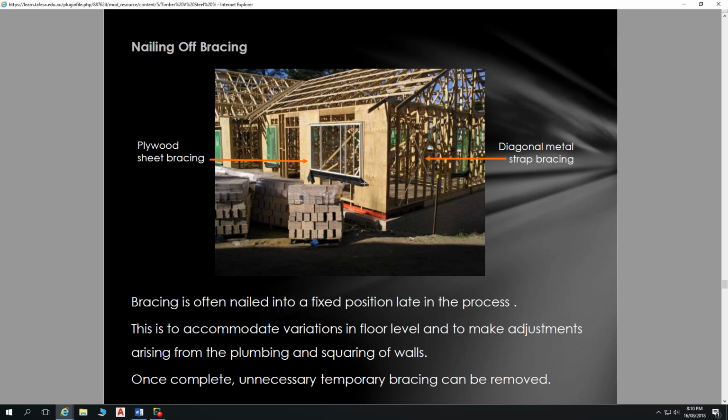Although plywood does have some sort of tolerance to moisture as well. But yes, it certainly gets wet. But the main thing that's an issue is if we go fixing weatherboards to this, we've got, say, a 10mm sheet of plywood happening there, and this bit we don't have 10mm sheet of plywood. We have to pack that whole piece out by 10mm. Or if we're doing sheet bracing here, then we have to do it all the way along that wall.